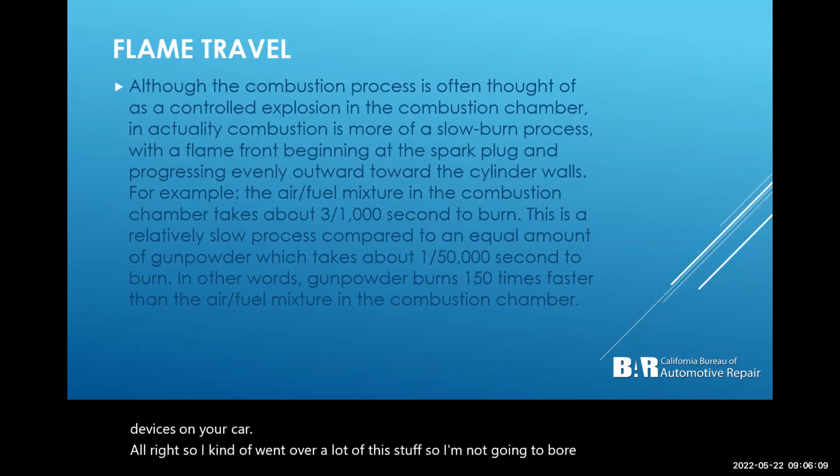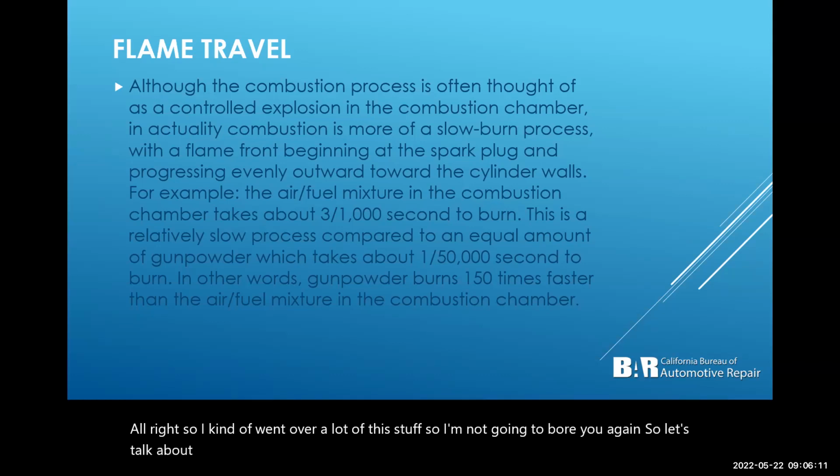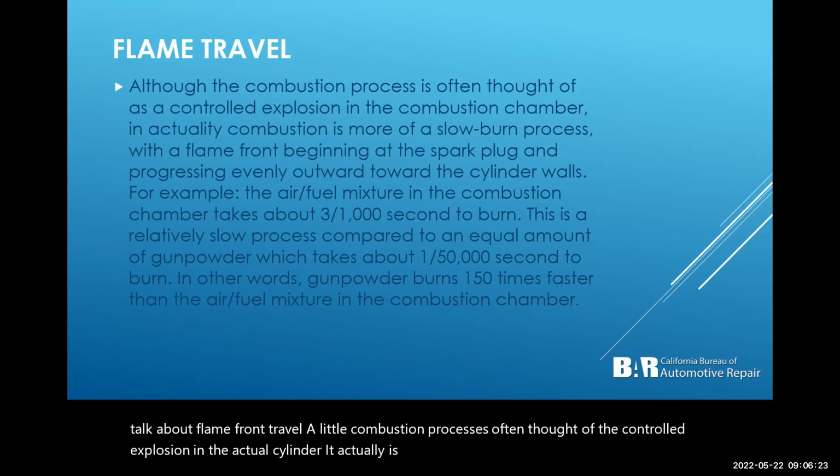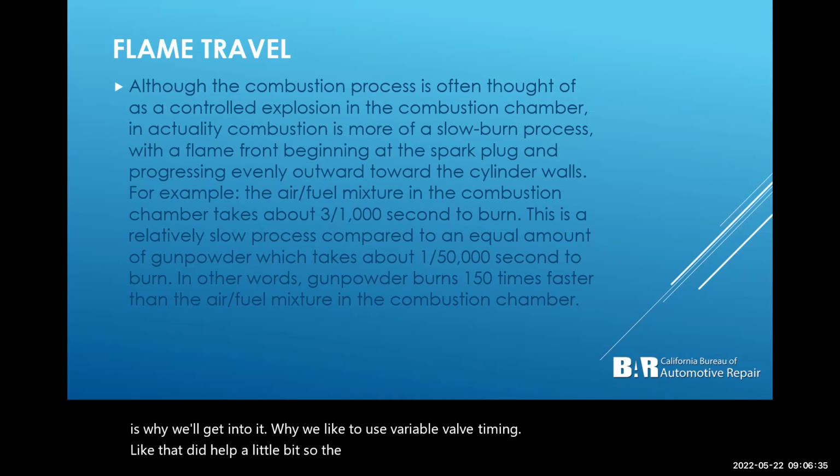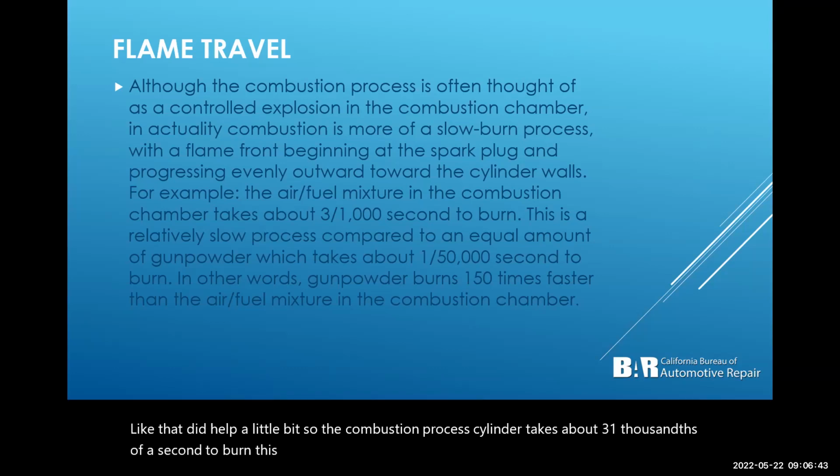So let's talk about flame front travel. Although the combustion process is often thought of as a controlled explosion in the actual cylinder, it actually is a slow burn process. And this is why we like to use variable valve timing, which helps a little bit. The combustion process in the cylinder takes about 3/1000ths of a second to burn. This is a relatively slow process.